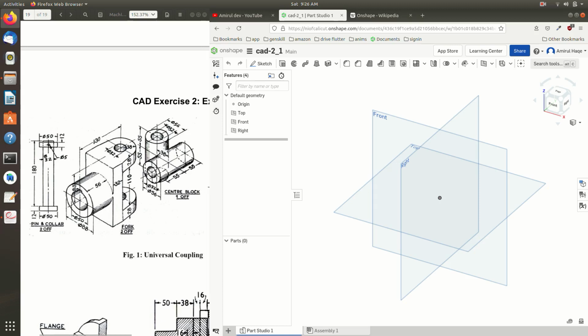There is a 56 dimension, right? You can take this axis which is parallel to the 56, and draw the view of this part. There will be a rectangle and a circle, and in this view, this entire projection will be a rectangle, and here there will be another rectangle. So let's start.